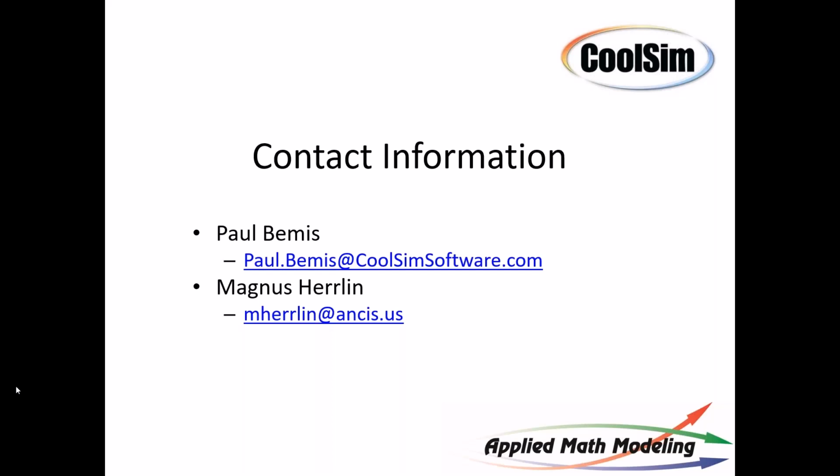And the question Michael Green had is, when leakage was repaired, I would expect the PUE to become more efficient. Is that a faulty assumption? Well, the problem, Michael, is that PUE is not that sensitive, unfortunately, to changes in things like that, because it's got IT energy in the numerator, and the IT energy tends to wash out improvements you make to cooling energy. I'm not a fan of PUE for that reason. It's fairly insensitive as a metric.